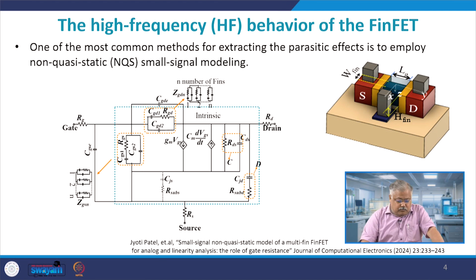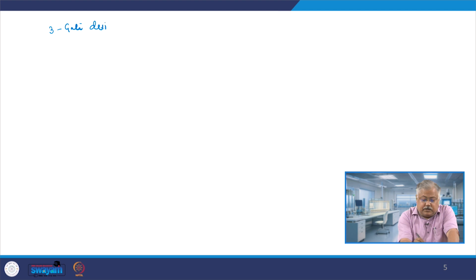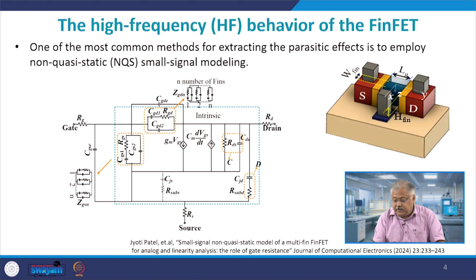We will come to this later on. Two things which you must be aware of is that if we look at, let us say we are looking at FinFETs, right. So FinFETs are basically tri-gate. These are 3-gate devices, right. These are 3-gate devices and tri-gate devices, and you can also convert a tri-gate to a double gate by making the top layer oxide thickness pretty small. As you can see here, the FinFET is there.